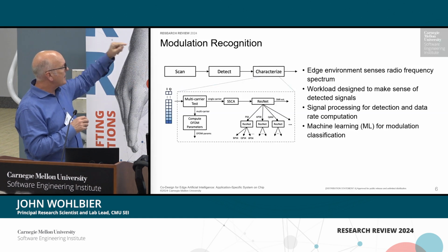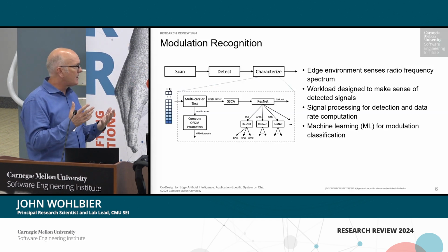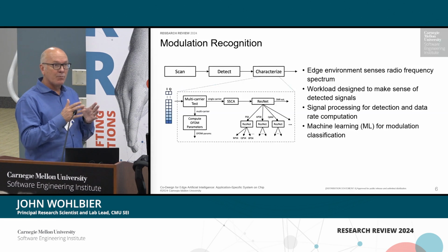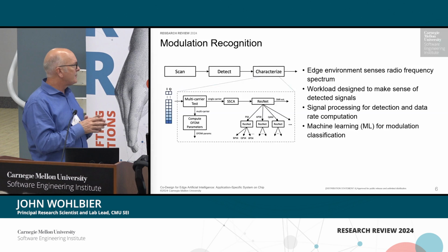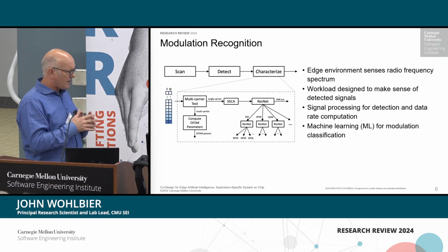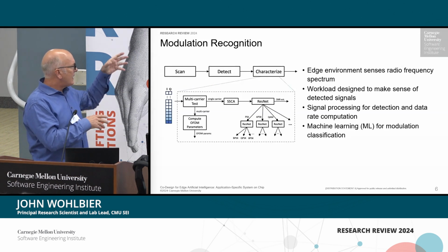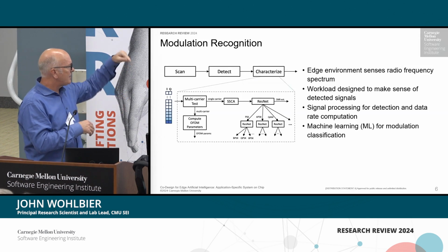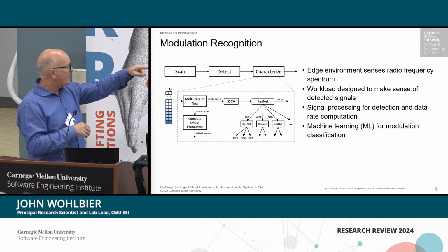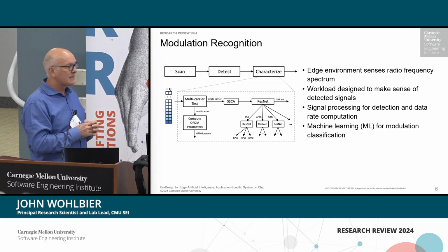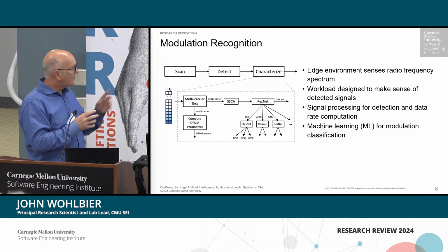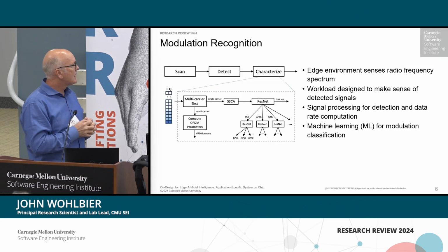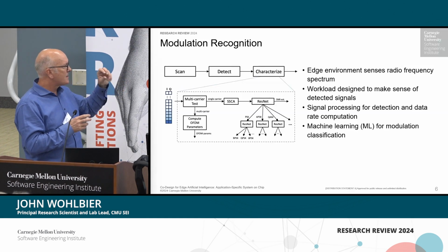So coming in on the left, the first thing that the chain does is it tries to find if there's a multi-carrier frequency kind of situation going on. So OFDM is the most common, orthogonal frequency division multiplexing. If it detects one, it spits out something. If it's a single carrier signal, it goes on to this thing called SSCA. That's the strip spectral correlation algorithm, and that's what we're going to talk about most today. That determines a